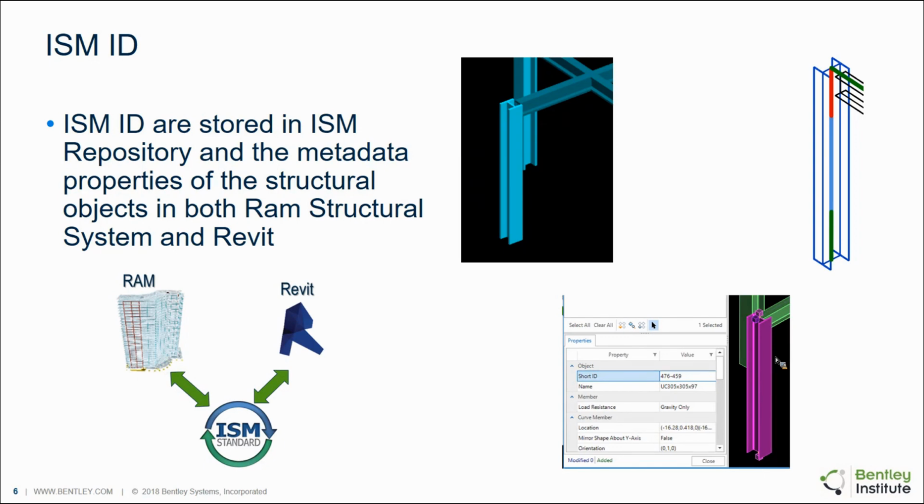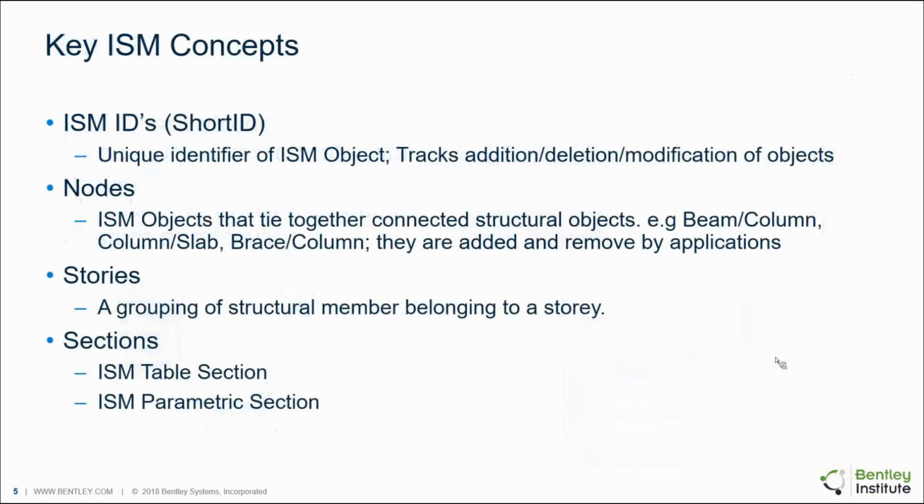Another reason why the ISM ID is important is that sometimes when you see error messages or warnings during your ISM import-export, they refer to the ISM ID of the object. And knowing that, you can find the particular object in Structural Synchronizer.